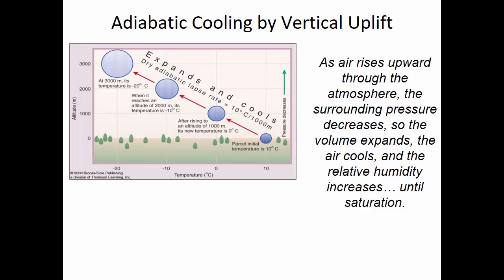if we have a tank of water and we go down through the fluid, here's location 1, here's location 2. The pressure increases as you go down through a fluid, right? For water, it's 9810 newtons per meter cubed. So for every meter you go down through water, pressure increases by 9810 pascals for every meter of depth.